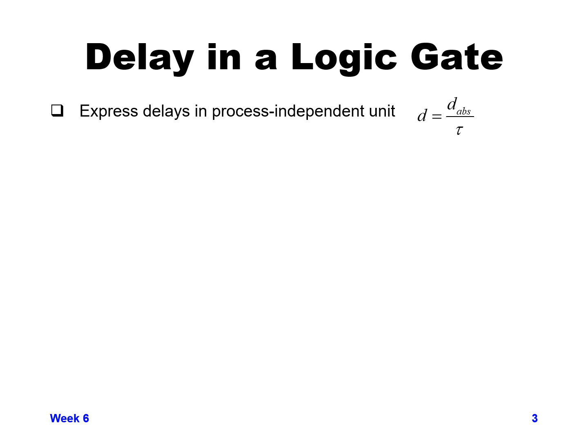So our delay D, as we're going to be calculating in all of the upcoming slides, is going to be the concept of the absolute delay, D sub abs, which would be how many picoseconds or nanoseconds or whatever it is that we're measuring, divided by a process dependent term called tau. And that way we'll get a normalized delay, a delay in terms of number of delay units